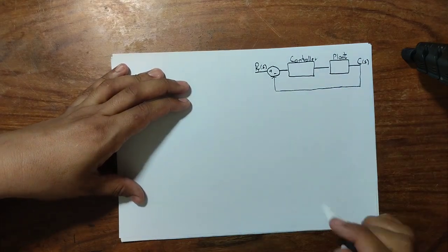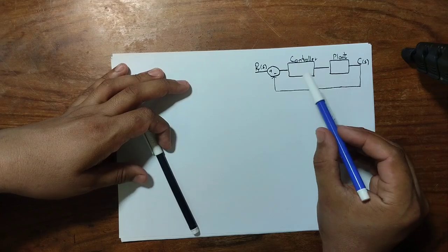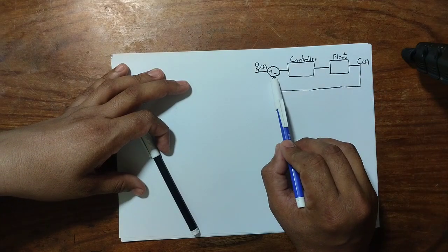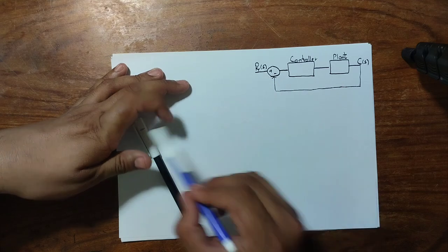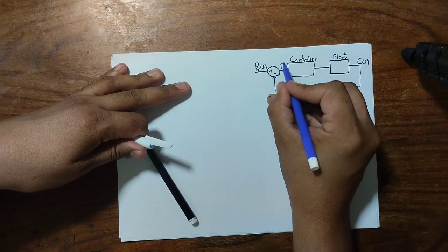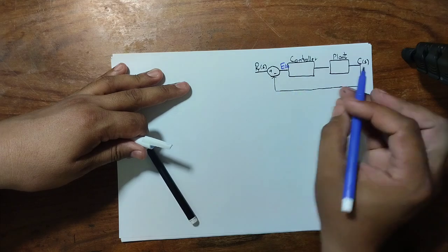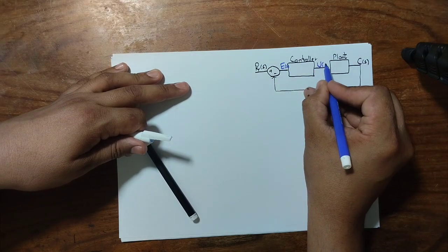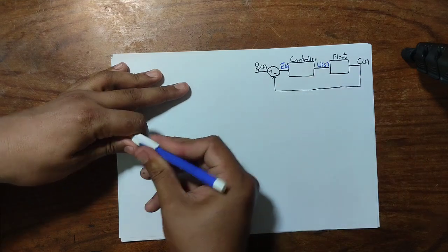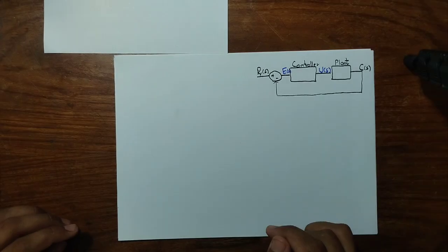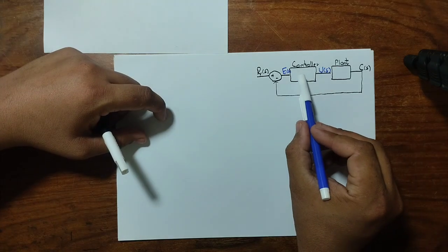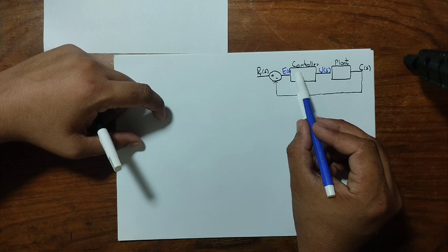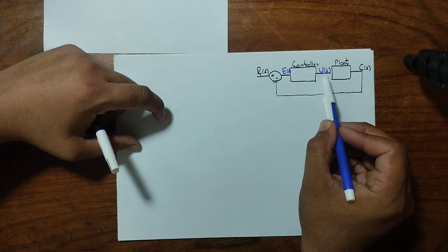So here we can see that we have devised a general feedback control system. In this diagram, we can see that we have an output that is fed back to the input side to compare it with the reference signal, and that will generate an error signal. Let's name it E of S. Then based upon this error signal, the controller will process this input and generate the control output. So here we have made a general representation for the controller, because we will use different kinds of control based on our requirements, and we will complete the design aspect of the control system.